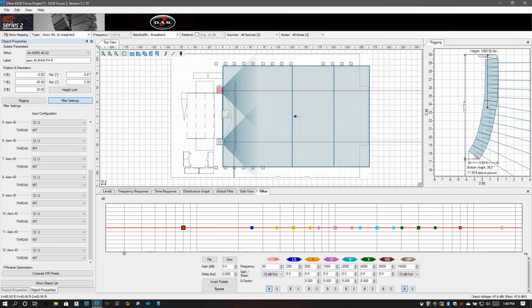We're going to put high pass at 80 and a Butterworth 24. Now we can't select Linkwitz-Riley Butterworth, but we just do the octave, the amount of cutoff that you would want. So I'm going to use Butterworth, negative 24 octave at 80 hertz. And if you look at the bottom, it's already bypassed.